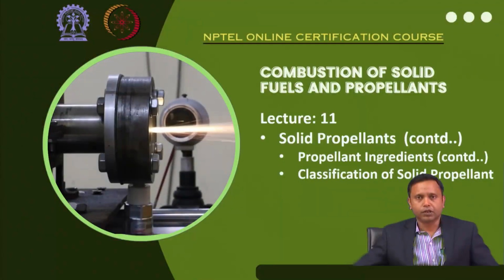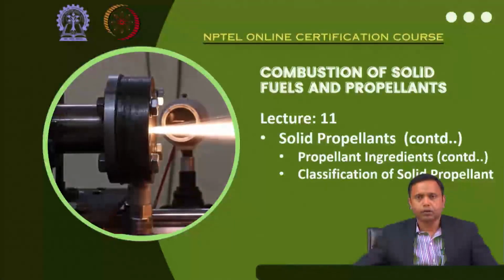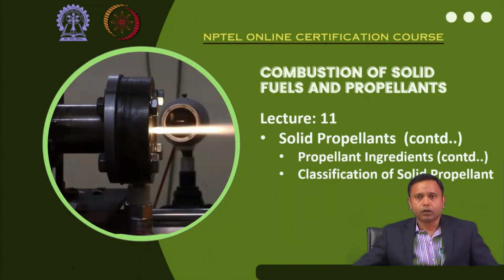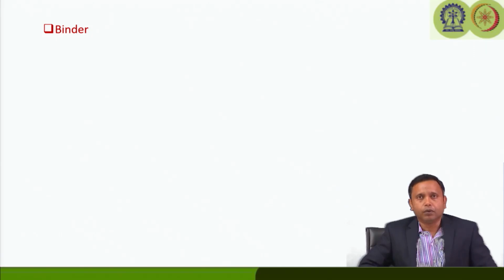Welcome back. We are discussing solid propellant ingredients in the context of solid propellants. So far we have talked about the different types of fuels used in solid propellants, and different types of oxidizers, like the inorganic oxidizers and the organic oxidizers like explosives. In terms of inorganic oxidizers, we have talked about the nitrate based oxidizers and perchlorate based oxidizers. We have also said that ammonium perchlorate is considered the workhorse oxidizer, because it is the most commonly used oxidizer in solid propellant rockets, and due to its high performance it is preferred.